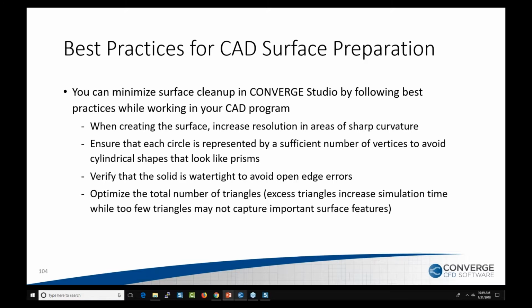If you export the geometry with your solids, then you may end up deleting a bunch of triangles, which you can do easily in Studio, but it will make your life easier if you export just the aero volume. Also, most of the STL export operations allow some sort of tuning knob, which you can use to control how many triangles you want in your final export geometry.